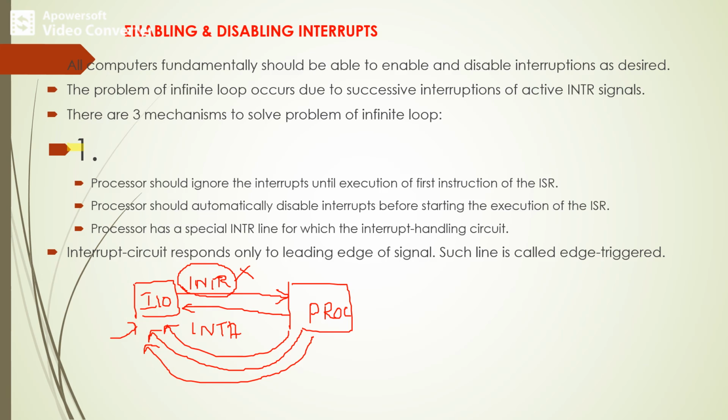So in case 1, the processor will ignore the interrupt request line, that is the INTR line, until the execution of the first instruction of the ISR.